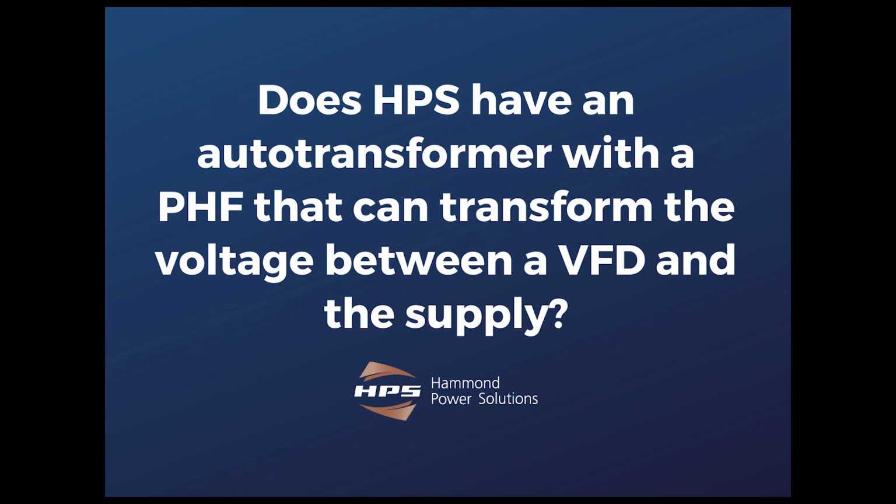You could, if you don't need isolation, also use an auto transformer. However, auto transformers aren't necessarily inherently rated for the harmonics you might see, albeit the harmonics in between it with a passive filter or active filter should be low. Would you agree with that answer?